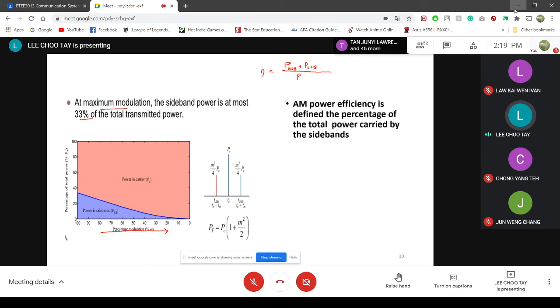You learned your filter design before, right? So let's take a simple filter, let's say a first order filter. What is the attenuation like? Attenuation for first order is minus 3 dB per octave or minus 20 dB per decade, right? Attenuation means reducing the amplitude of the frequency component by so much.